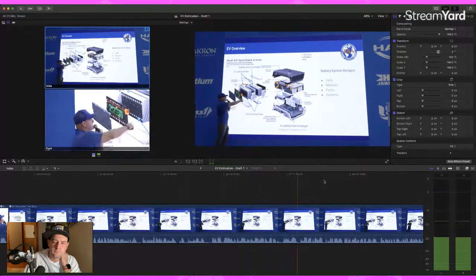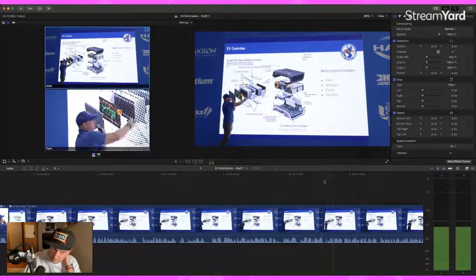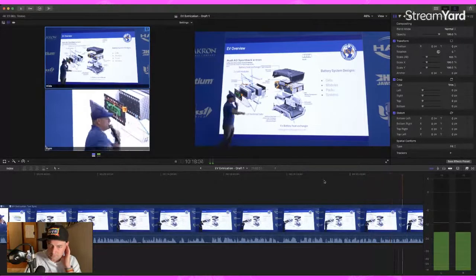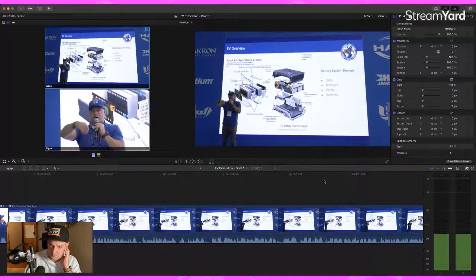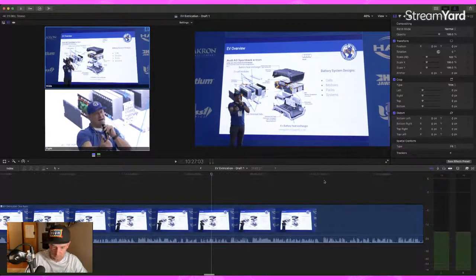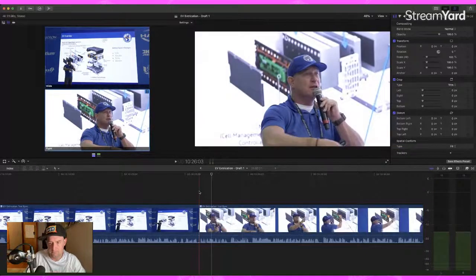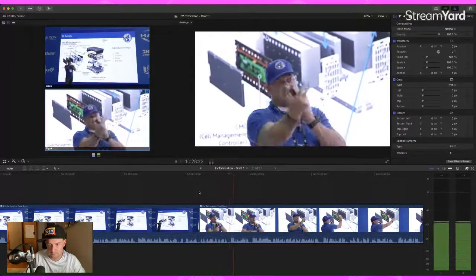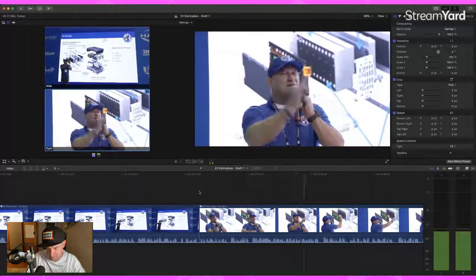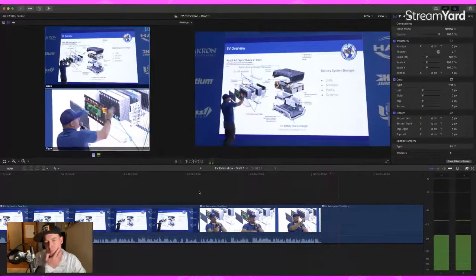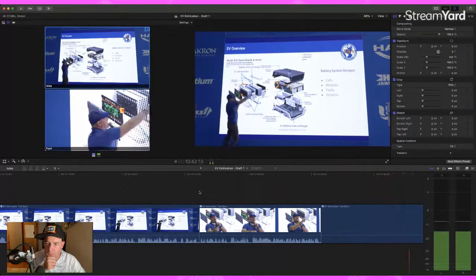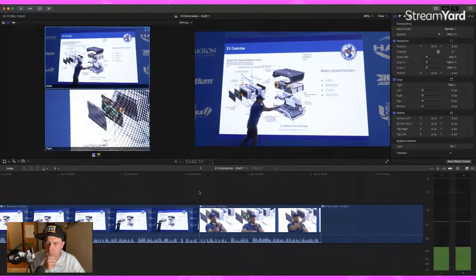So if you look at this slide, the small black component here with the silver tabs on it, that would be an anode and a cathode silver tab. What we do is we take that box, it may be about the size of a VHS tape, and we literally cram as many of those cells into that box as we can. Those could be prismatics, those could be pouches, or those could be cylindricals. Then we want to run wire leads off of those anodes and cathodes, and that gives us our positive and our negative tabs. Then I'm going to cram as many cell packs into this box as possible, and this is called a module pack. Then I'm going to take module packs, and I'm going to throw them into what's called a battery pack.